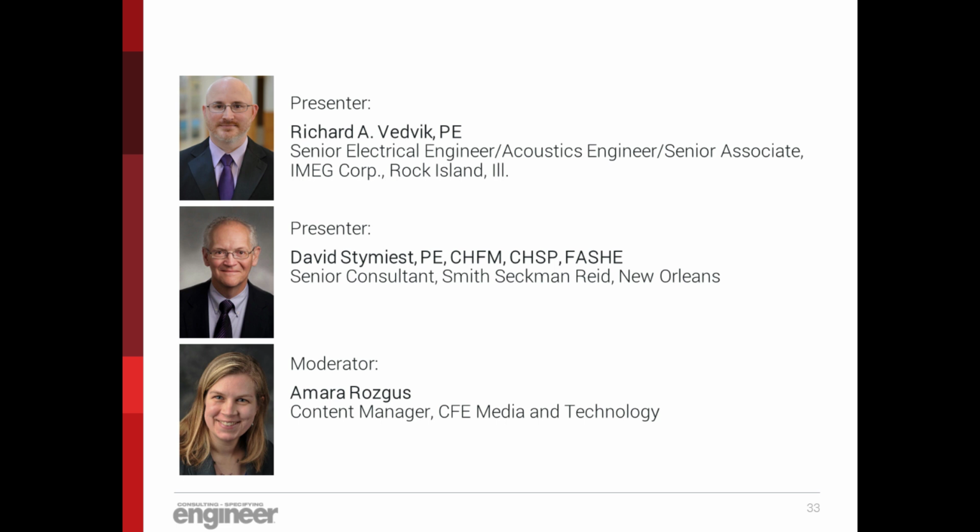Absolutely. And we get this question a lot. If you're looking at resiliency of a hospital system, maybe you're doing a greenfield standalone hospital and you get to build this thing from scratch. And the utility says, we can give you 2 feeds coming in. Well, that's great. I would like to have 2 feeds coming in. But maybe they say, I can only give you 1 feed and I can't guarantee it's going to be up all the time because we like to have tornadoes here. In that case, the facility might say, well, let's go ahead and do some tier 4 big, 15 kV gensets that just take over for the utility. Now, what does that do for the rest of your discussions that we've been talking about on what kind of transfer switch branches you'll have?